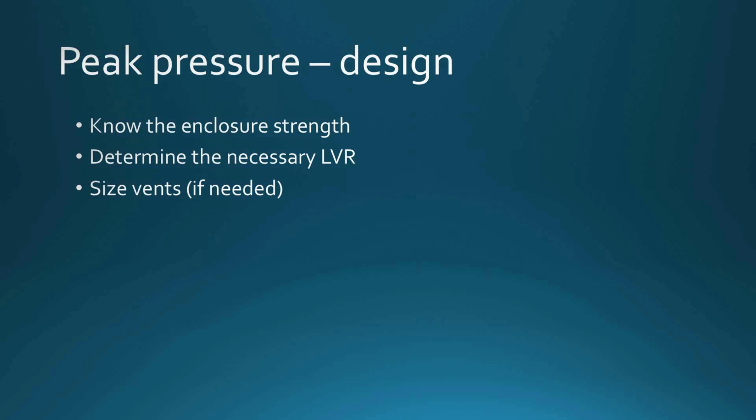In some cases, adding a little bit more agent is going to solve a whole lot of problems. And I know for sure that the biggest single problem that people have out there is getting small enclosures tight enough that they will pass the hold time requirement. And I've seen people spend $250 on a 250 square foot enclosure, an entire week trying to get this enclosure tight enough. Now we discover not only did we have to spend a lot of money on unnecessary air sealing, but we also had to put in a vent on top of that, which may not have been in the